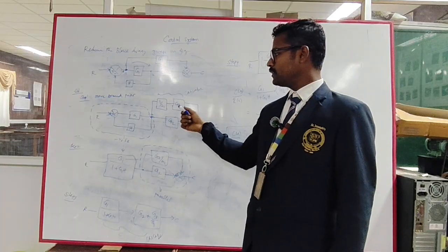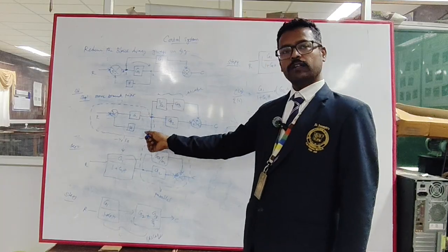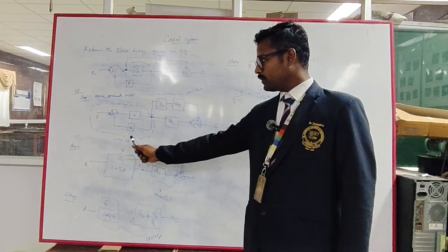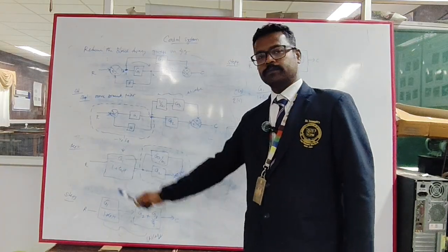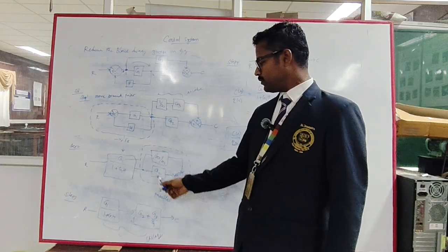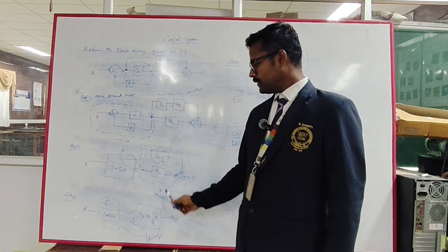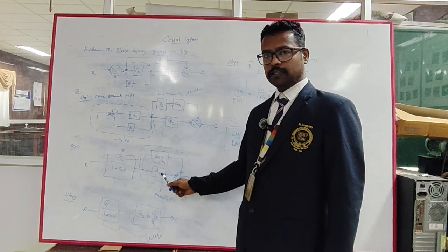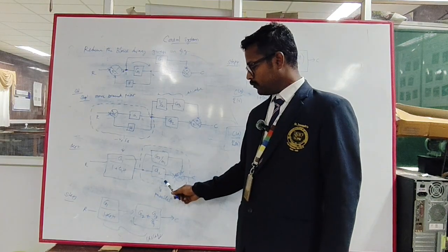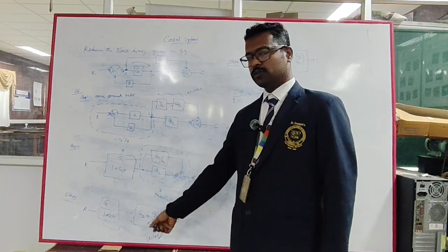We are reducing both things in a single step. Nothing to multiply here, you will get this one, and for the negative feedback you apply the formula. So you will get G1 divided by 1 plus G1H1, since it is negative feedback, meaning you get a positive here. After that, these two things are in a parallel connection, so we reduce this in step 3. Parallel means we just add the transfer functions of the blocks. Both are added up here and you will get this one.